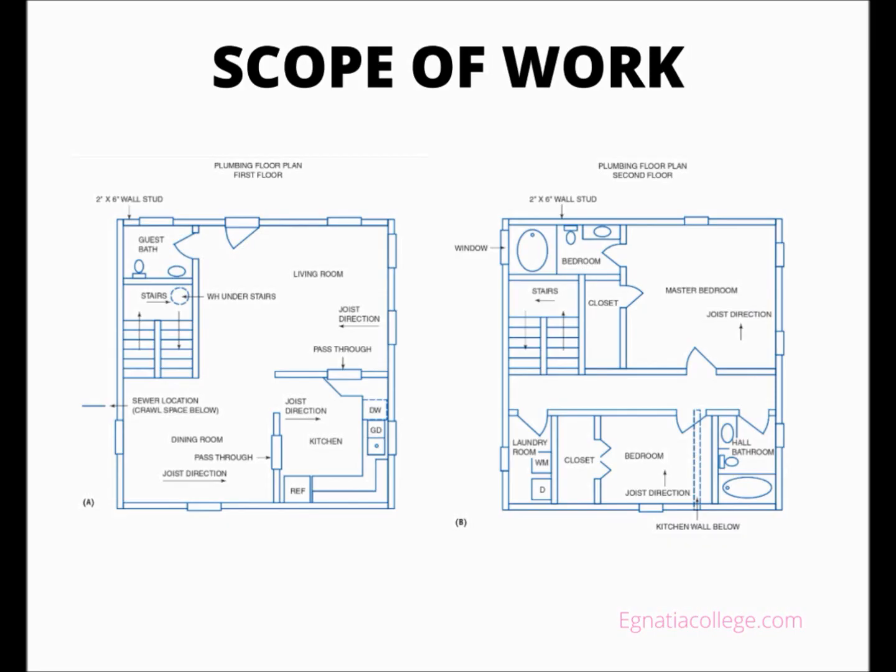The unfinished crawl space area below the first floor would be a desirable pipe route due to its ease of installation. If the area below the first floor were a finished basement, the pipe route would have to coordinate with the design intent of that space. The location of underground vertical riser piping penetrating the concrete floor must take into account the pipe routes established to serve upper floors.